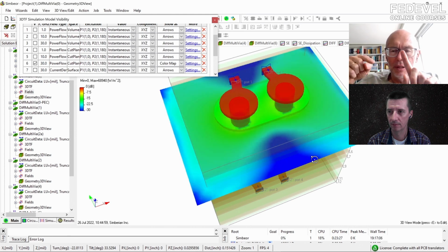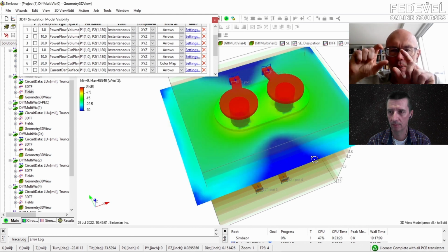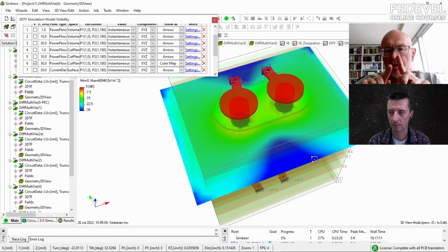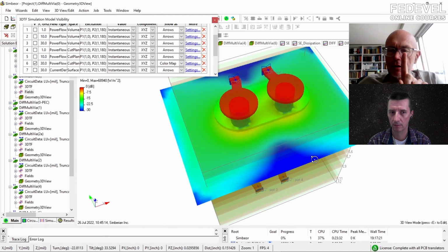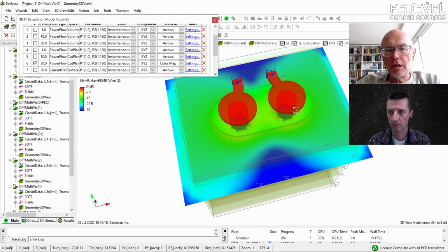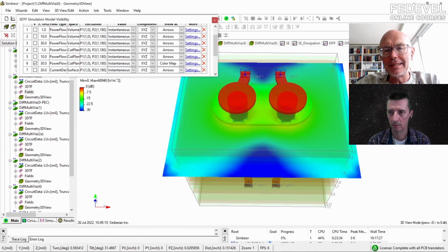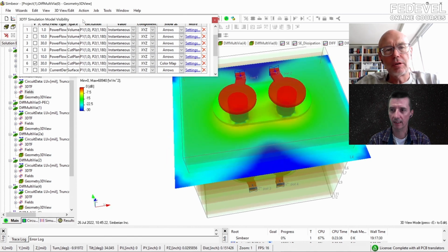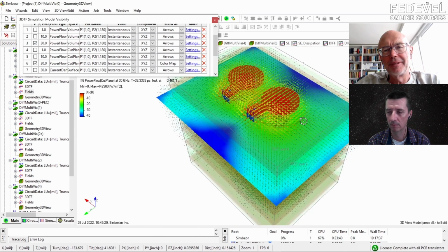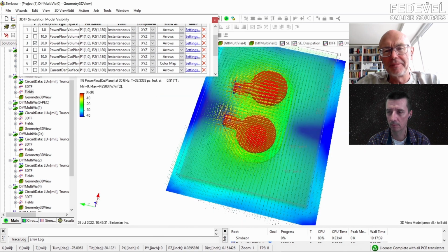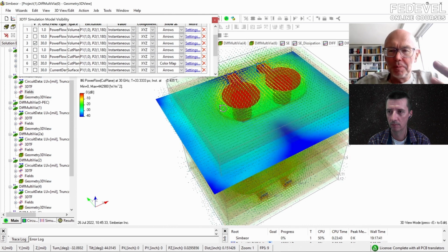If you model a phased array of two currents in opposite directions, just at some frequency, and take a look at the radiation pattern, they will not radiate perpendicular to the location, but they radiate sideways. Right here, what you see, the vias are radiating sideways at 30 gigahertz. They really kind of cancel each other in the middle, but not on the sides. So they're not radiating this way, they're radiating sideways. So now you know where to put the stitching vias.